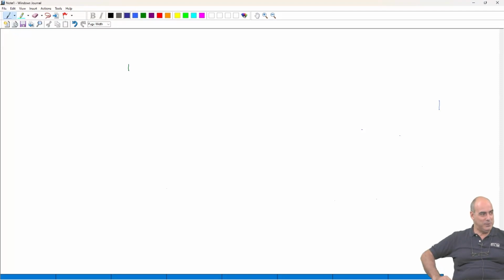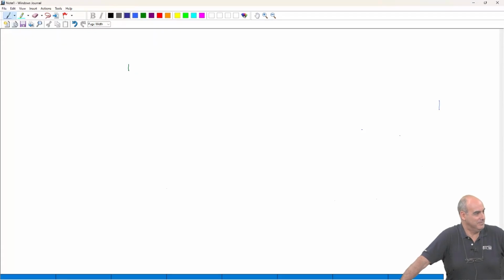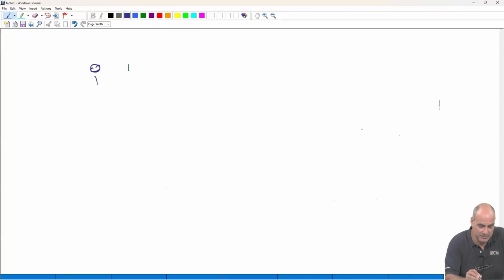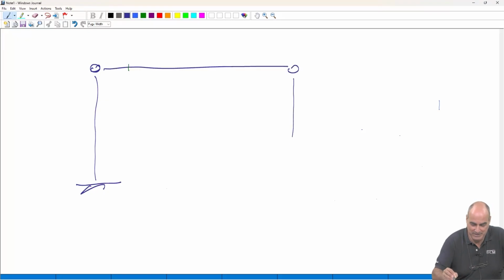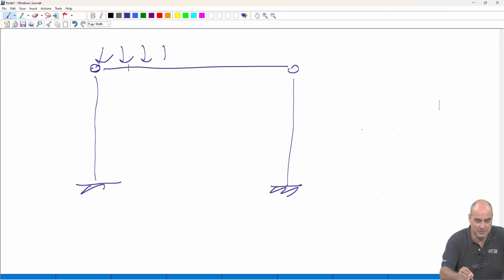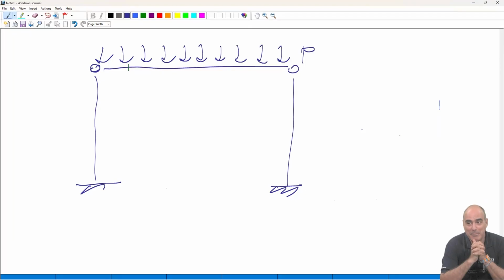And how can we do that? By playing with the effective length. And what does the effective length depend on? It depends only on the end conditions. Okay? So you start from here. This is your building. And so, end conditions. And what can you do for end conditions? Making the pin connection at the top fixed.